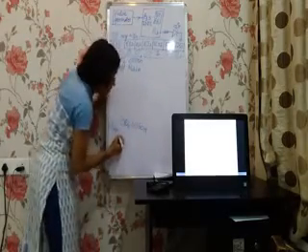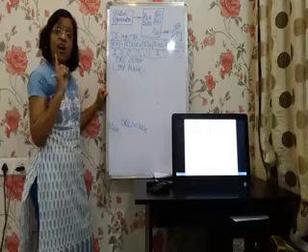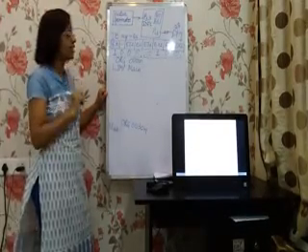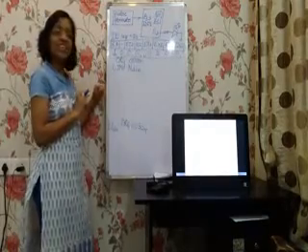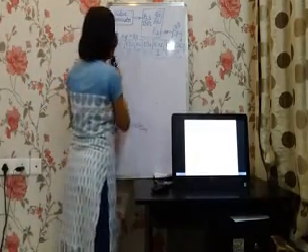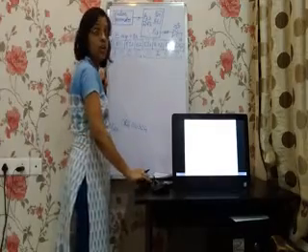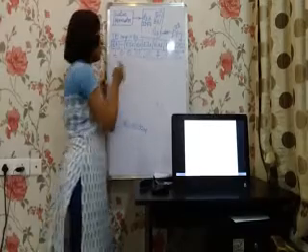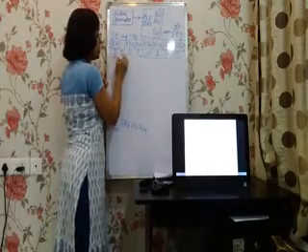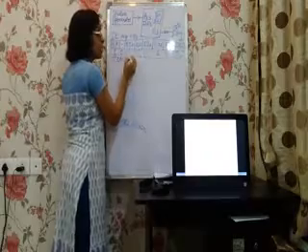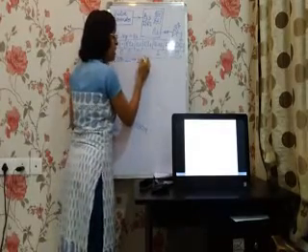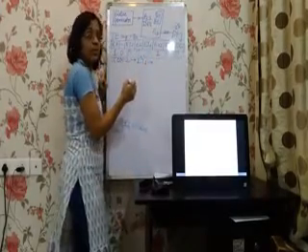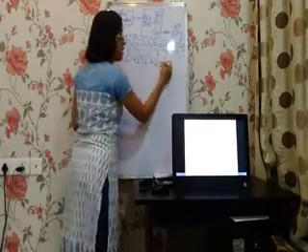But before configuring IE, I also need to tell that INT1 is defined as an edge triggered interrupt. Now how will you define INT1 as edge triggered? You have to configure the TCON register. TCON register also we have seen. In the TCON register, TCON.2 corresponds to IT1. IT1 is the INT1 type control bit. We have to keep this one to indicate edge triggering.